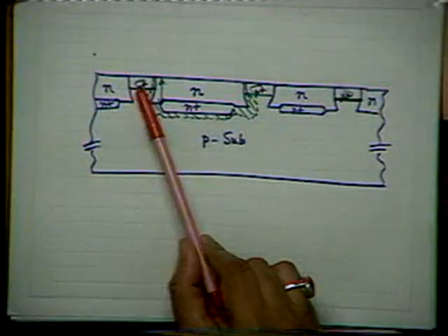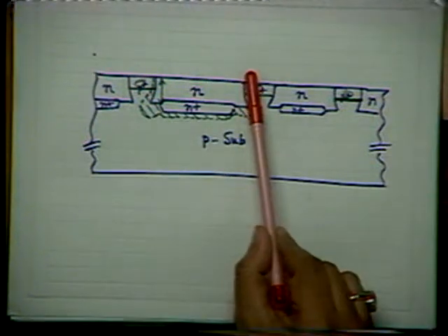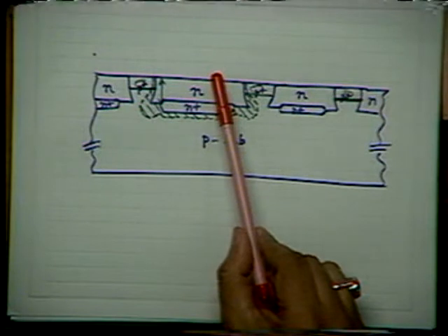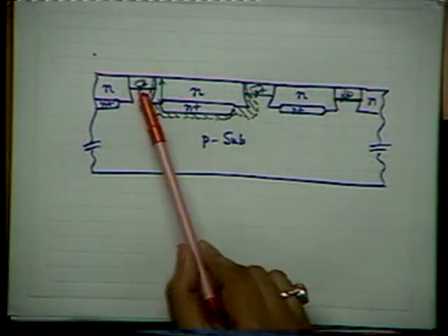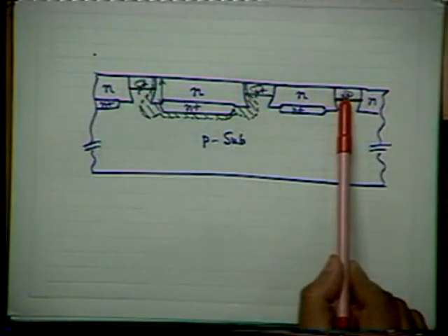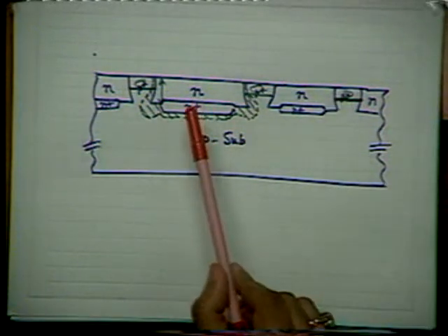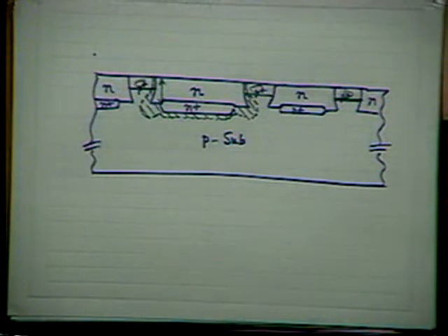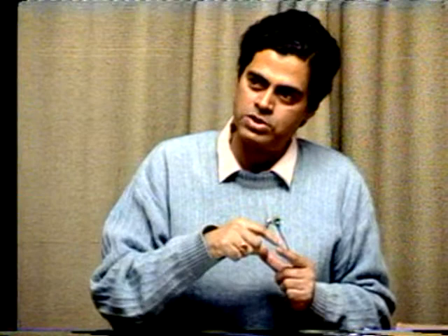And what will happen? Silicon will be oxidized, but nitride has a very low oxidation rate, so nitride will not practically be oxidized. Only the silicon here in these regions will be oxidized. Now, as silicon is oxidized, it is not an oxide deposition. This is an oxidation. Please remember, silicon reacts with oxygen to produce silicon dioxide. It is not an additional oxide film. So what will happen as a result?